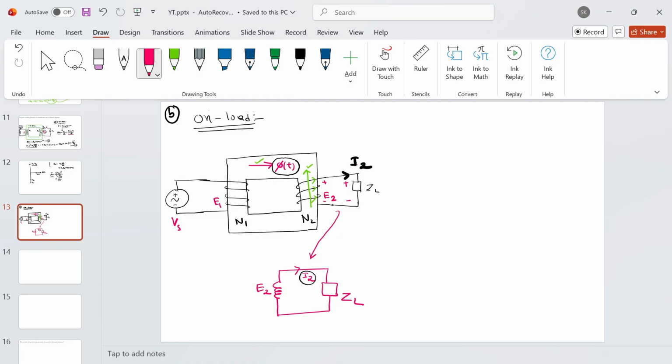But there is something more that we also need to discuss. Now we are aware of how this voltage will get induced, the current flow and all. Now let me tell you one more thing. The moment you have this opposing flux, it is basically reducing the total core flux. Then what will be the case?